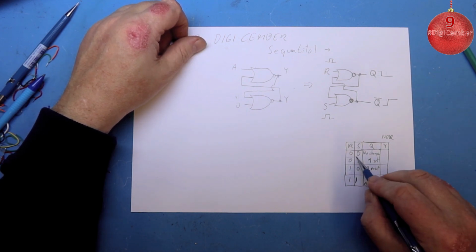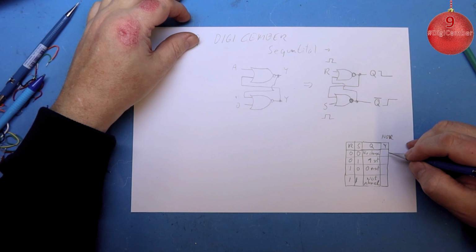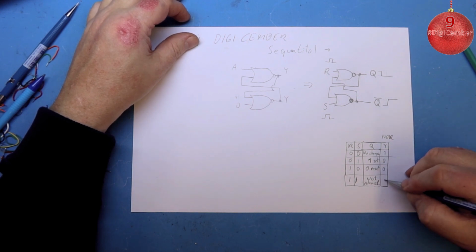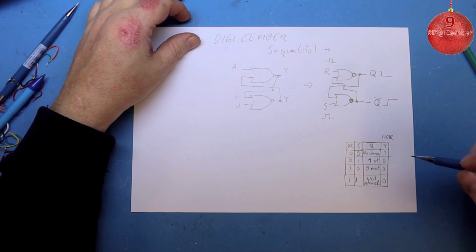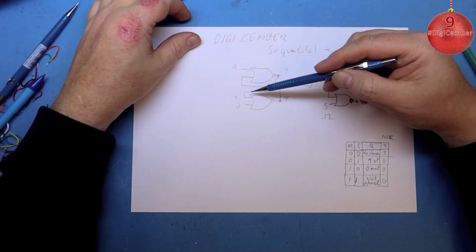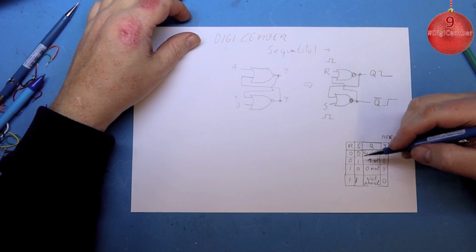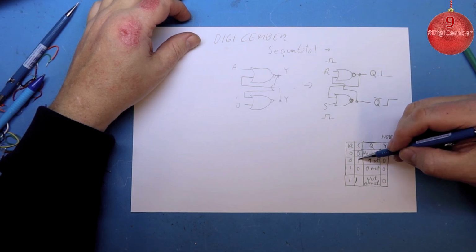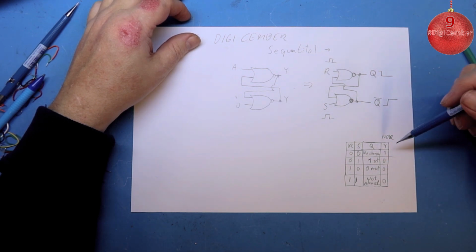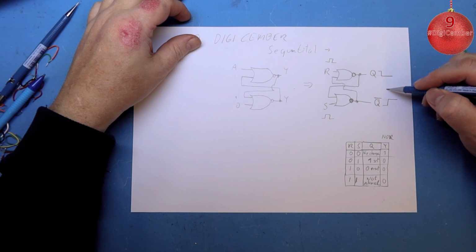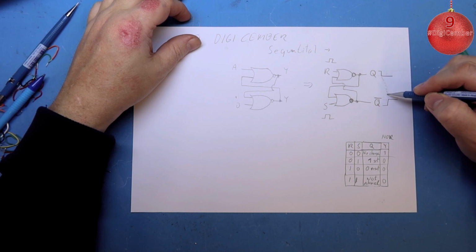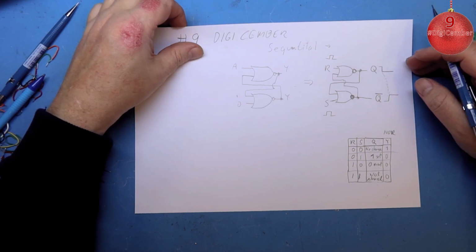So if we combine this with the gate from the NOR gate, you can see that in itself the NOR gate will give this kind of result, because you are taking the output here and chaining it back to here. You actually get it to keep its state, and this is the simplest form of memory there is. Sorry, it was a bit confusing with this, but this should actually be the same timeline. I don't know what went wrong today with this.